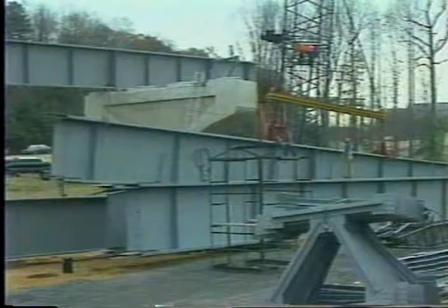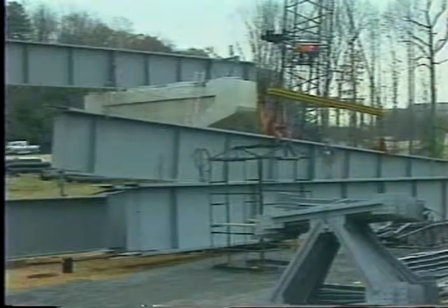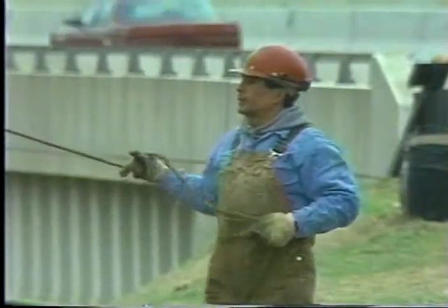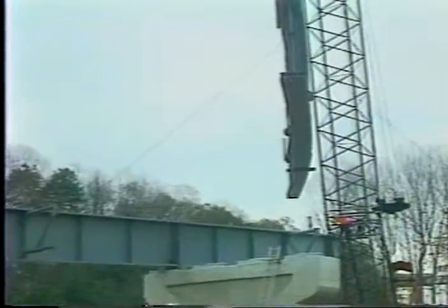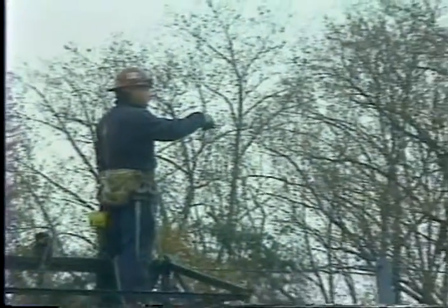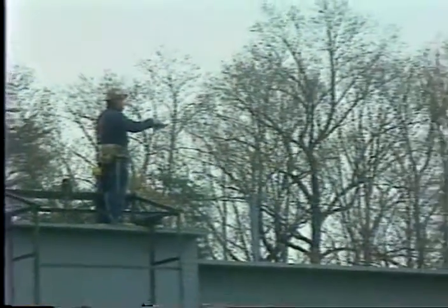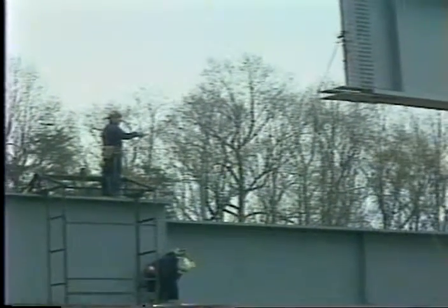Span lane is the number of spans multiplied by the number of traveled lanes of each structure with a clear span of 6 meters or more. It is used for structure inspection on major contracts.